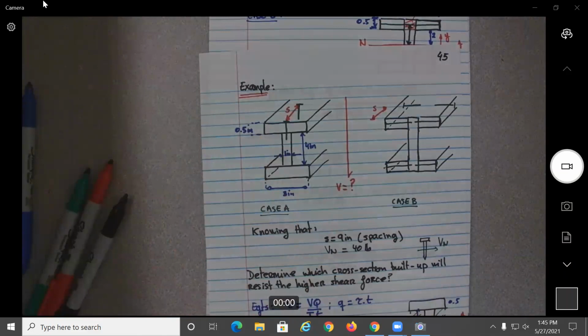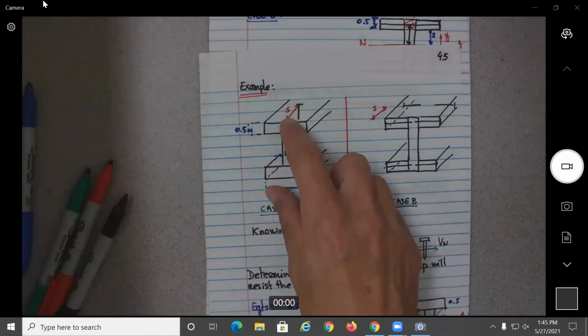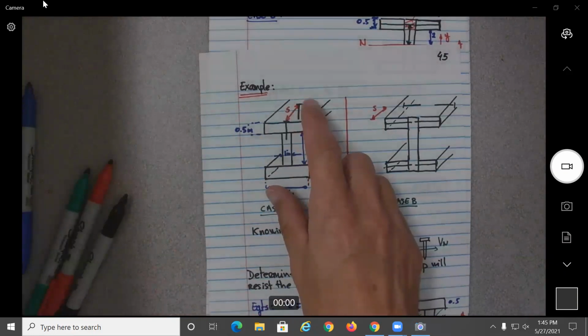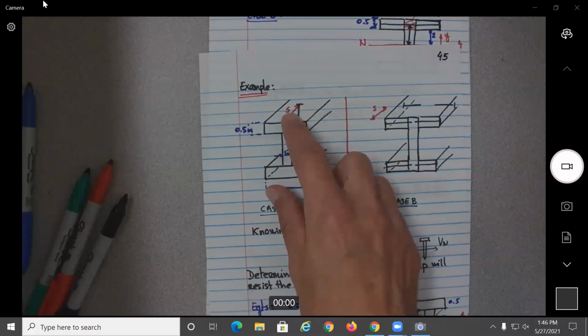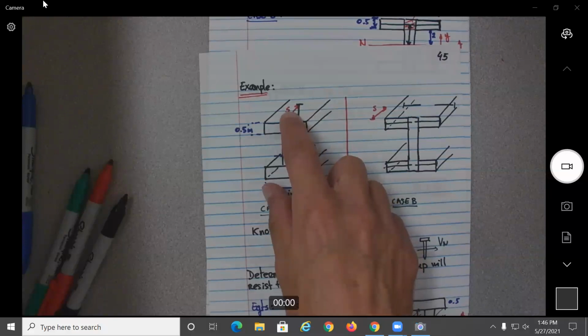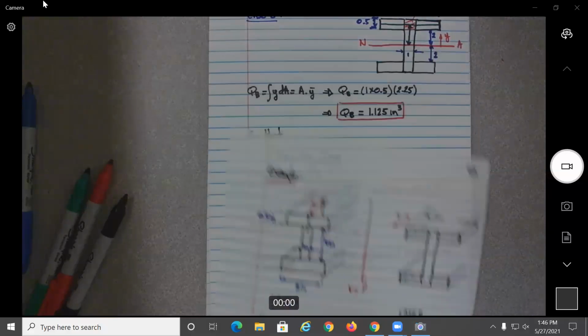All right, then what could be another decision you can make? Maybe you want to optimize, maybe you can change the spacing, no? Maybe you want to say, okay, I still want to use this construction, but I want to make it a bigger safety. So what can you do? You can actually reduce the spacing. You can put more nails, and then what will happen if you look at the equation?